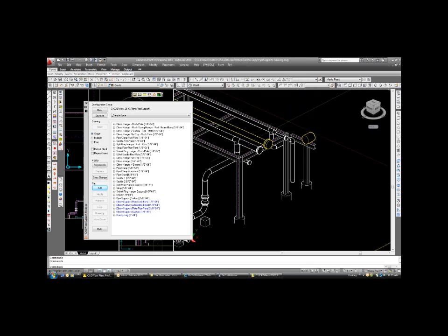This is where you'll control what and where you'll insert a particular pipe support. I want to start off by explaining a couple things. Let's explain right here the PSA file. The PSA stands for Pipe Support Assemblies. The pipe support assemblies are where you store your configuration for all the pipe supports you'll use on a project. This sample PSA is, for example, a list of pipe supports that are available to you through this one registered file.